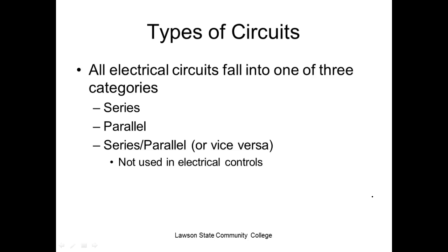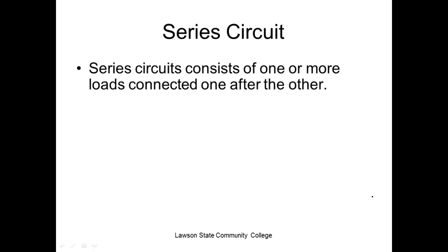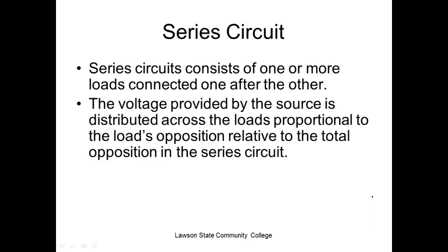And you're not going to have to solve for I or E or P or anything like that. So not used in electrical controls, guys. So here's a series circuit. Everybody okay with that? Everybody knows that? One load feeds into the other. The voltage is divided in the source proportional to the load and proportional to the total opposition in the circuit.